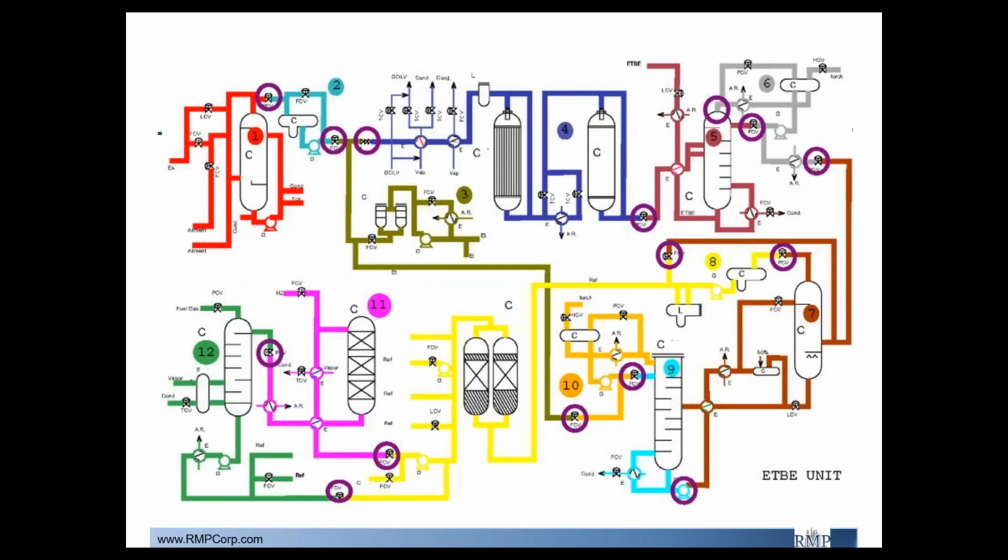So this is an example of a P&ID that's been broken down into different nodes. Obviously, this is a fairly complex system, so for any P&ID that looks like this or a little bit more complicated, there are going to be more nodes, which means that the importance of each valve, each tank, each column, whatever you have in your system, labeling them, making sure that the configuration is according to what the P&ID says is that much more important. So the more complex the system becomes and the more intricate the nodes are, the accuracy of P&IDs becomes more and more important.